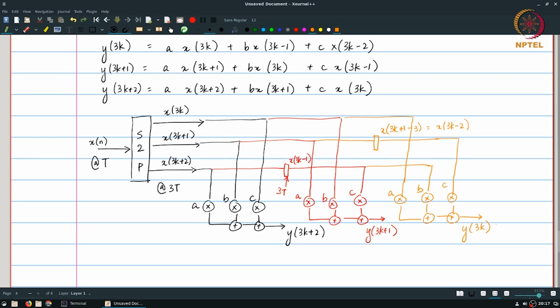So the question that would naturally arise is, what exactly have we gained by this entire process? In order to do that, let's highlight the critical path that we have over here. We can essentially go through this path, which is Tm plus 2 times Ta, or equivalently through this, or equivalently through any one of a number of other paths also that works. All of these paths that are highlighted have the same delay, which is basically Tm plus 2Ta.